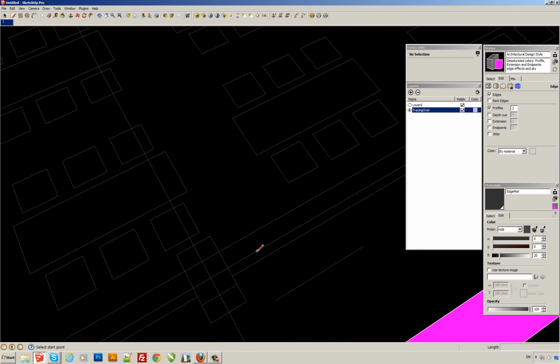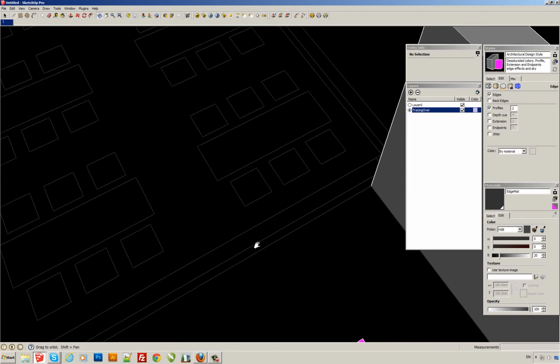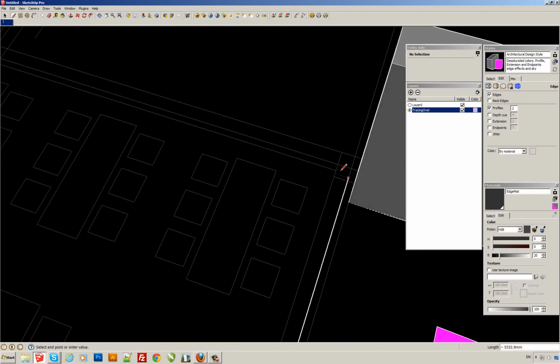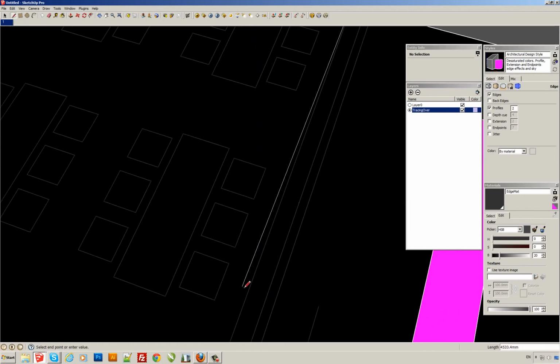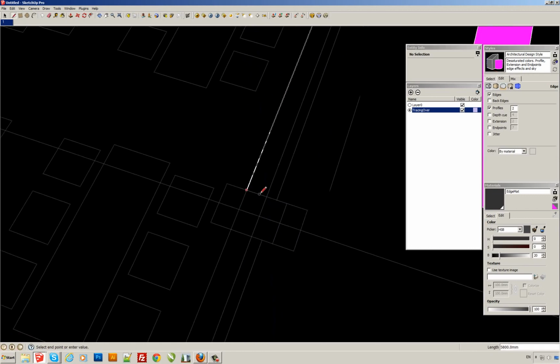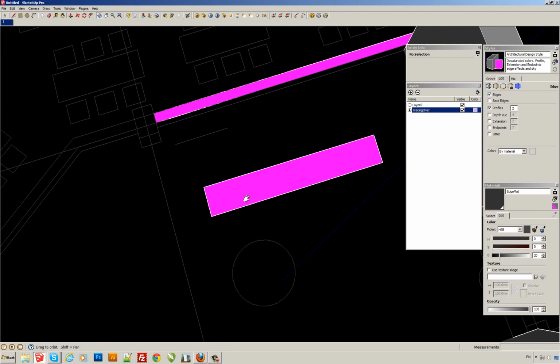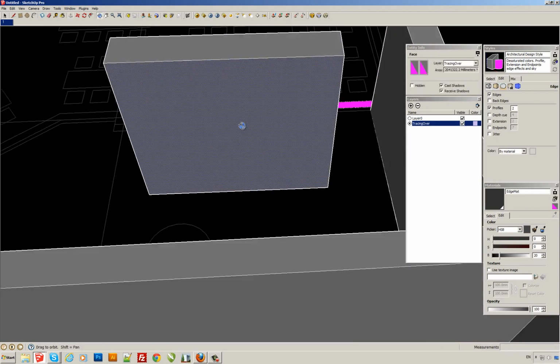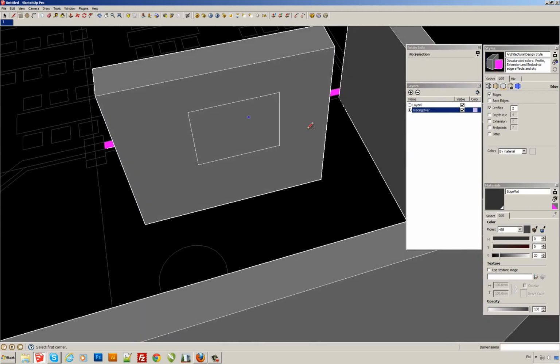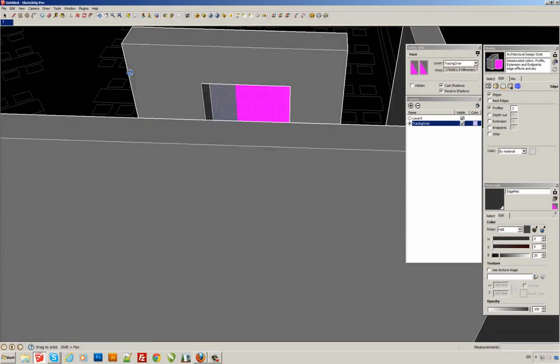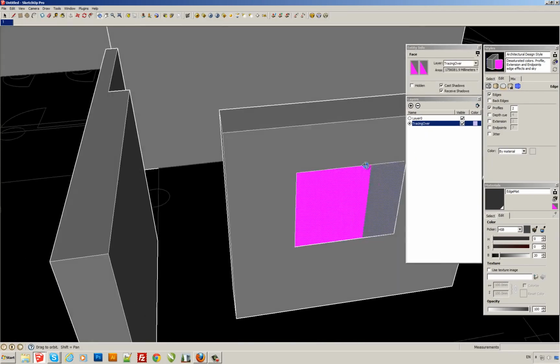Snap to some point on the line which is involved in the crossing, and keep the shift key. For example, this wall is drawn unparalleled, so you can face such problem.